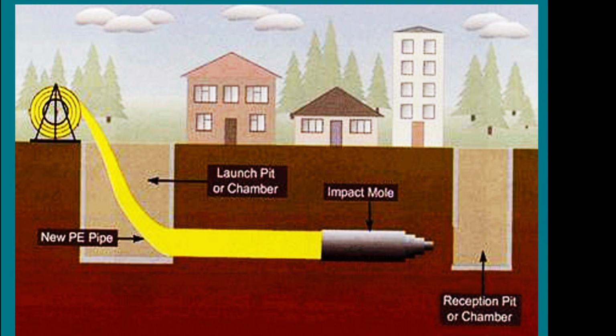After that, the pilot well is extended to a necessary diameter by reversal of the rig with compaction of soil. At the same time or after preliminary extension, the pipe is jammed through into the finished well. The impact moling plant works without applying bentonite mortar. The borehole wall keeps stability due to the compacted layer of soil.